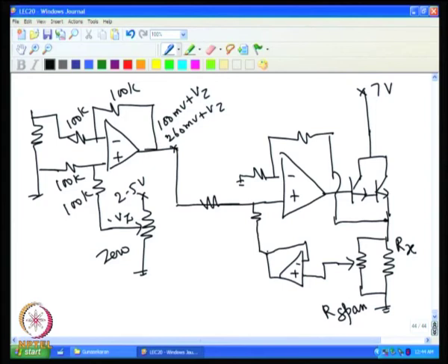The same current source can now be used to get 4 to 20 milliampere current depending on this voltage. So, for example, here we can have all resistances equal, example 100 K. For a simpler argument, I remove this and put the thing straight away here.